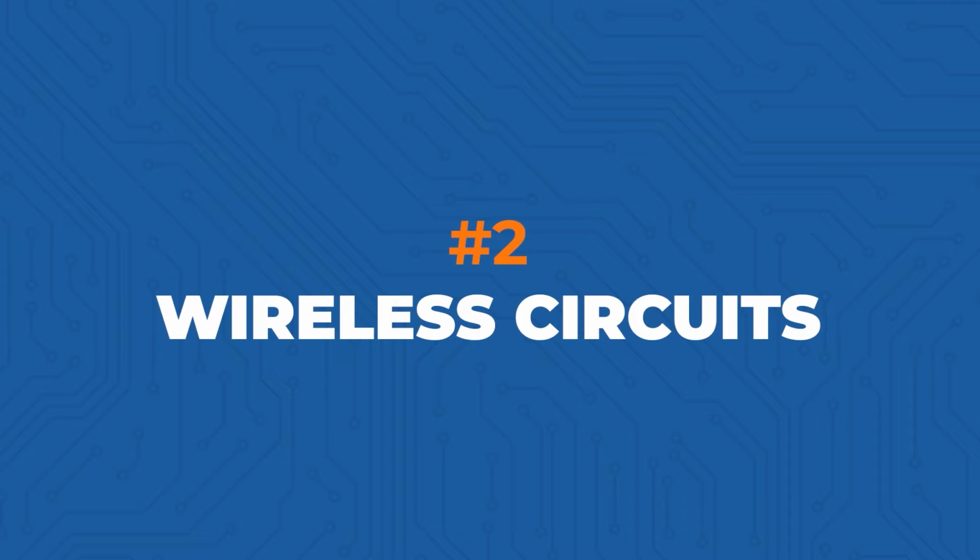This is one of the reasons it's always usually best to use modules for any wireless functionality. Two reasons: pre-certified modules simplify the certification process for your product, but they also eliminate all the design complexity and risk associated with wireless circuits. For a fully custom wireless circuit, that's extremely complex, and you want to make sure you bring on an RF engineer to at least review the design.